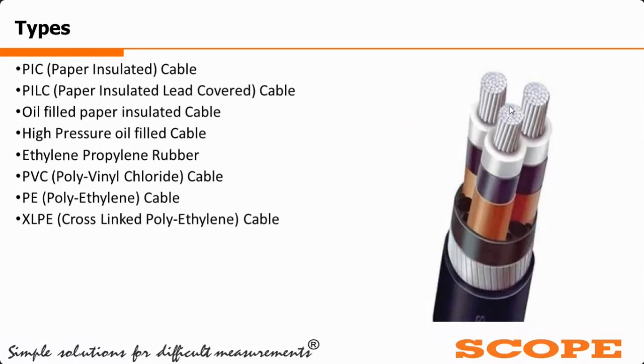It also has better aging characteristics, less susceptibility to water treeing compared to polyethylene, and low cracking. So the XLP insulation is also flame proof. That's why XLP insulation is now widely used for EHV transmission too, up to 400 kV applications.